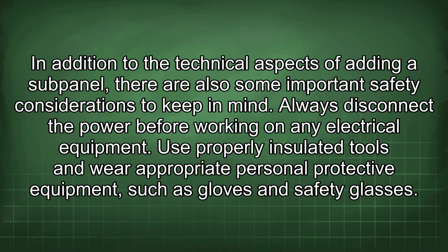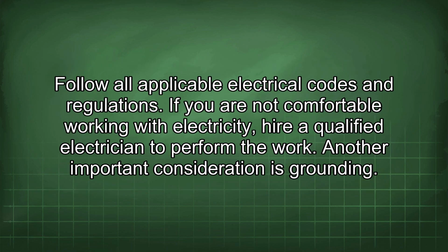In addition to the technical aspects of adding a subpanel, there are also some important safety considerations to keep in mind. Always disconnect the power before working on any electrical equipment. Use properly insulated tools and wear appropriate personal protective equipment, such as gloves and safety glasses. Follow all applicable electrical codes and regulations. If you are not comfortable working with electricity, hire a qualified electrician to perform the work.